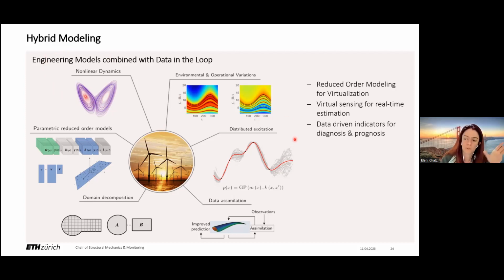the fact that our loads, which are, by the way, never easily measurable, you cannot promise to very precisely measure a wind distribution along an excited system, the traffic that crosses a bridge, the wind that is loading a bridge, and so forth. So our loads are not precisely measured, and they're also distributed most of the time. And our measurements that I mentioned before are usually sparse. They're also corrupted by noise. Most sensors have to deal with the fact that we do not have perfect instruments. We have some sort of disturbance or noise levels that we have to deal with in our simulation.